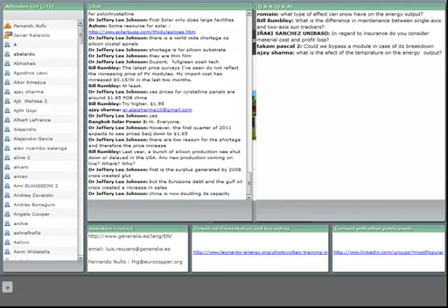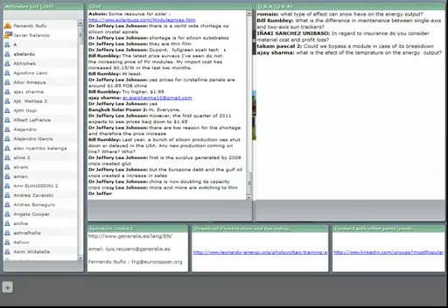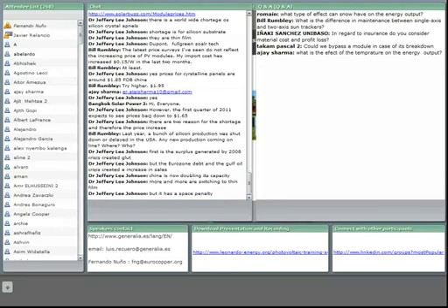Normally, for crystalline modules, we can consider that the losses might be about 4% for each 10 degrees over the 25 degrees of standard conditions. And for the thin film modules, these temperature losses, or this ratio, is lower, so we can expect just 2% of losses for each 10 degrees that the temperature goes higher.